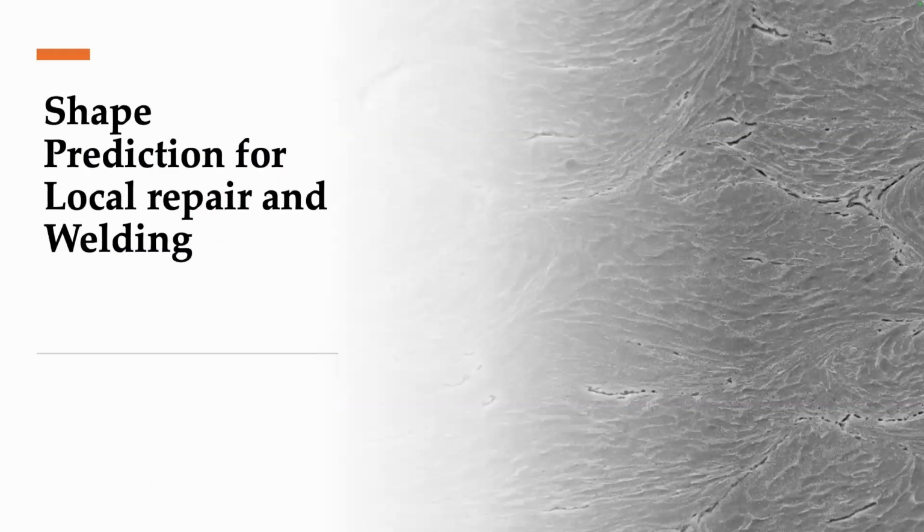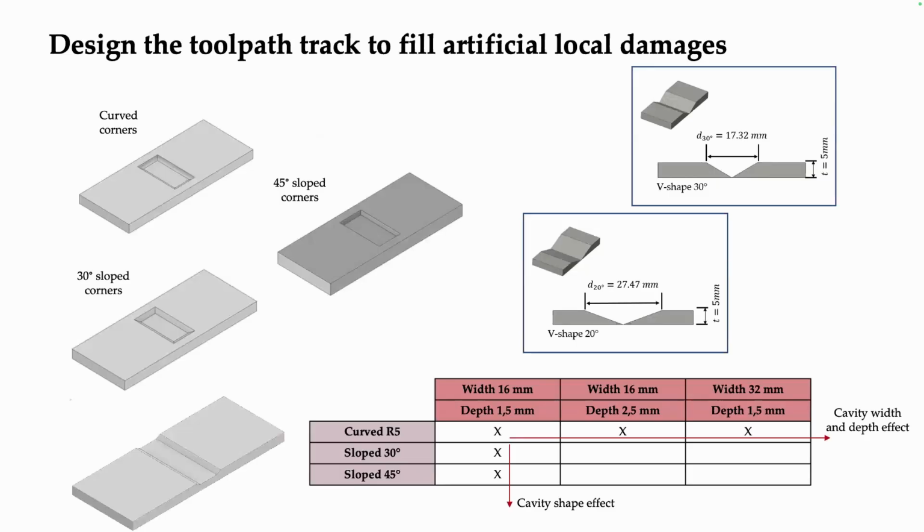To conclude my talk, I'm giving you one slide where we are trying to develop and use this code not just for additive manufacturing, but also for local repair and for welding. So we are adapting this code also for cases where we have small cavities that could be local or through cavities, or even for different geometries of welding, where we can use the advantages of cold spray for eliminating any heat-affected zone to do repair or welding.